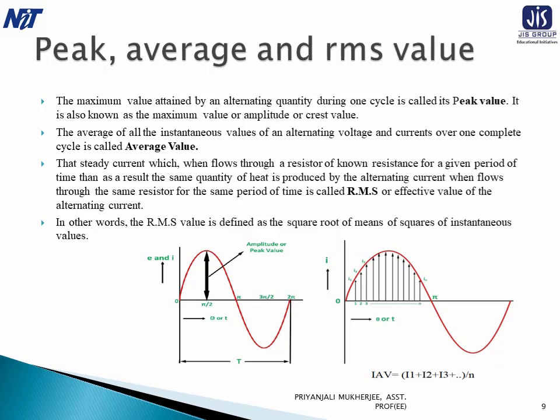In the case of symmetrical alternating current, symmetrical means one whose two half cycles are exactly similar, whether sinusoidal or non-sinusoidal, the average or mean value over a complete cycle is 0. So the average or mean value means the value determined by taking the average of instantaneous values during half cycle or one alternation. For unsymmetrical current, such as half-wave rectified current, the average value is determined by taking the mean of instantaneous values over the whole cycle.